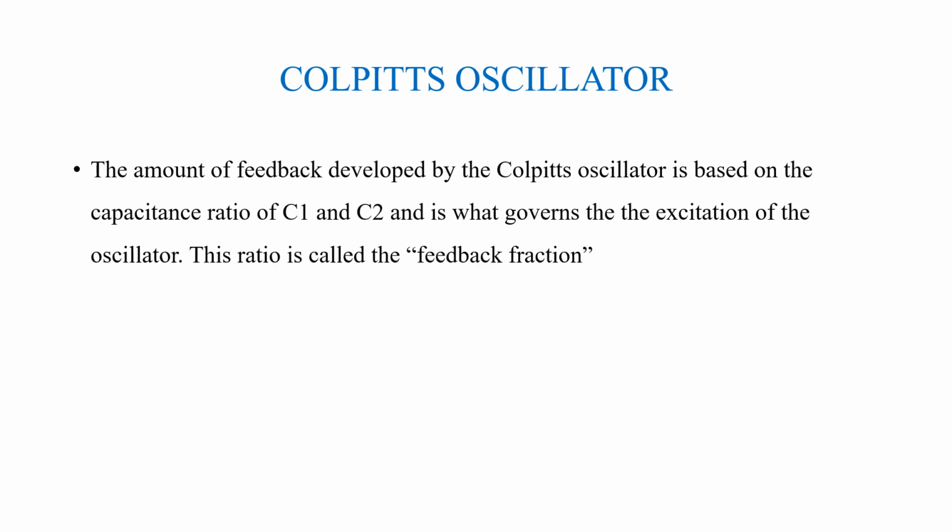The amount of feedback developed by the Colpitts oscillator is based on the capacitance ratio C1 and C2, and it governs the excitation of the oscillator. This ratio we can call as feedback fraction.